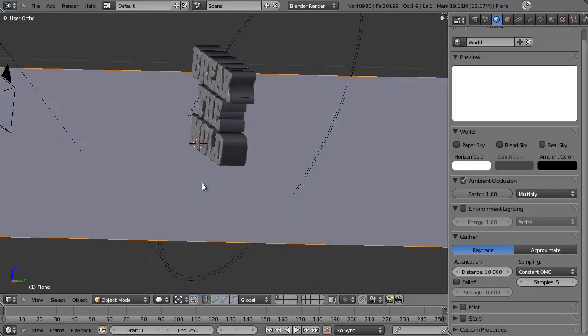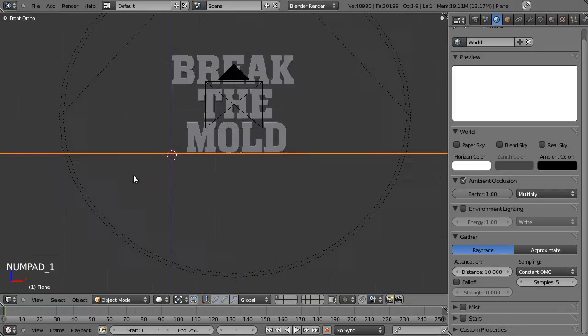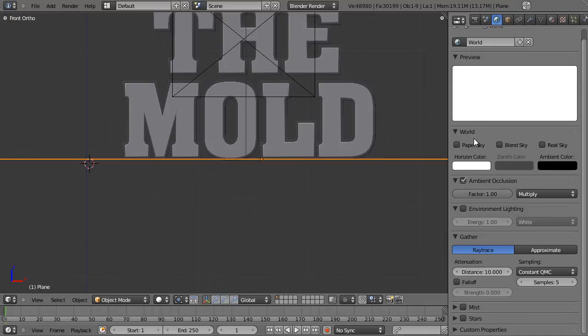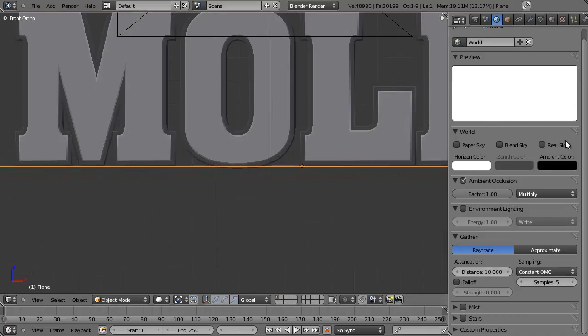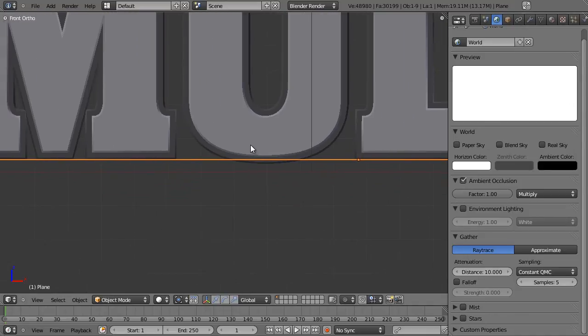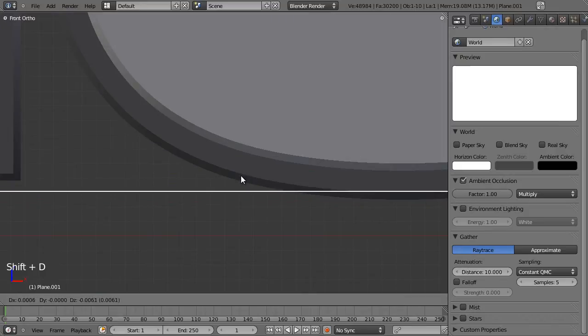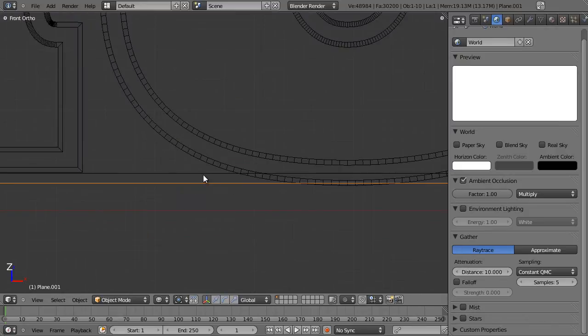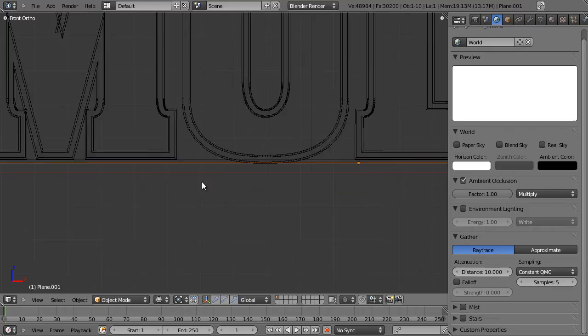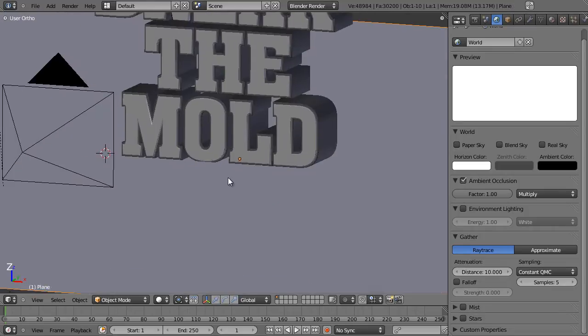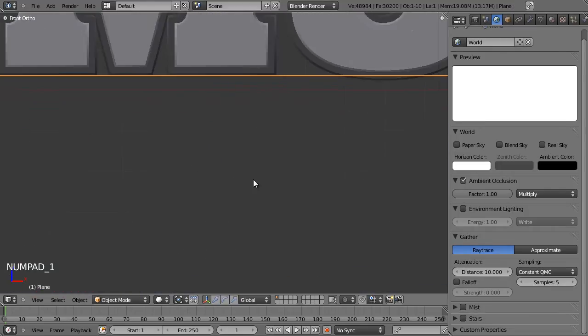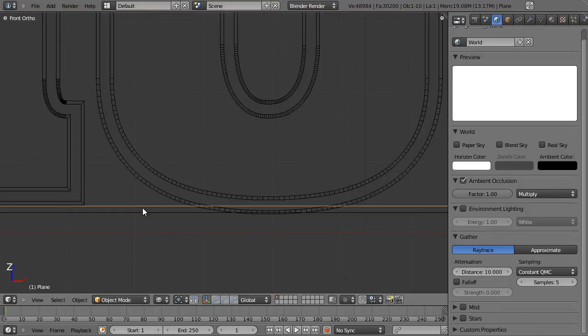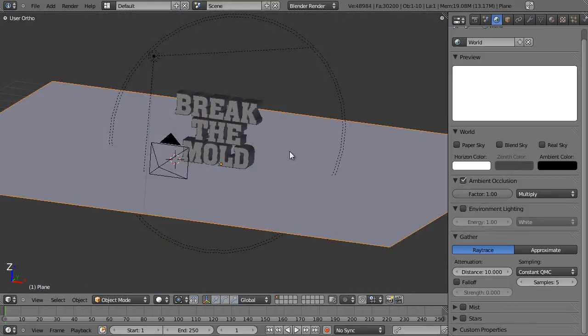So to do that, there is sort of a bit of a problem, because with that shadows only option applied, we can't actually add any textures or anything to it. So we actually need to create a duplicate of the ground, okay? So now we've got two ground objects there. It can get a little bit confusing, but for this type of effect, it is required. So basically, I'm just going to select the top ground object there now.